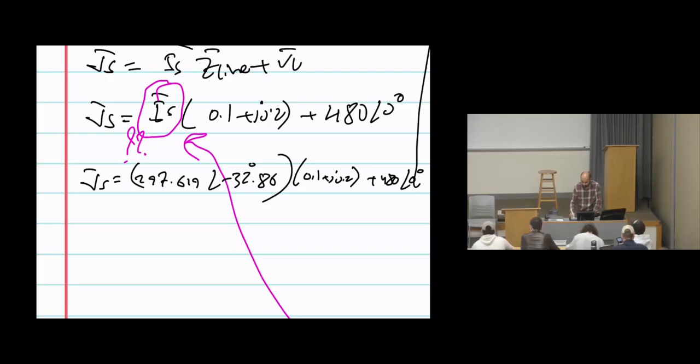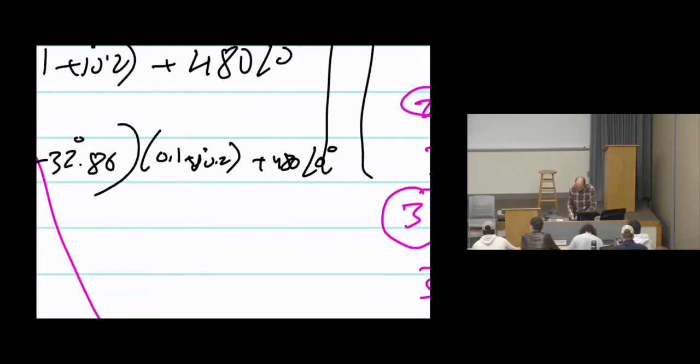Then, when you put this in the calculator, this shouldn't take more than 30 seconds to insert and get the answer. And sometimes when you put 480 angle 0 in the calculator, it will give you an error. Some calculators do this. Why? Basically, 480 angle 0 is the same as 480 without angle.